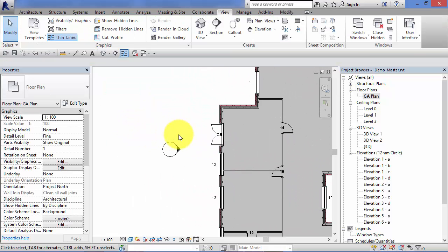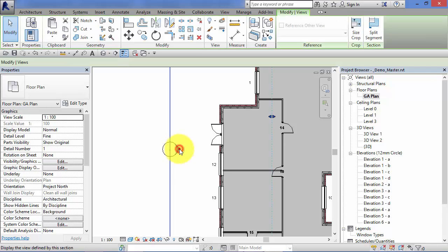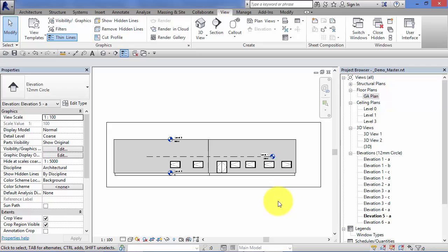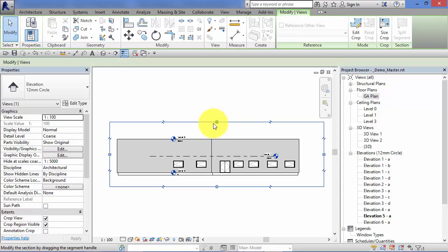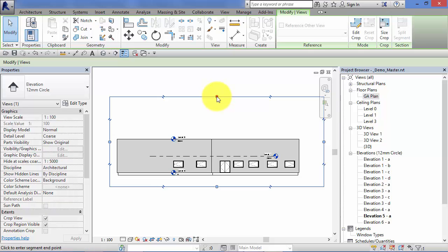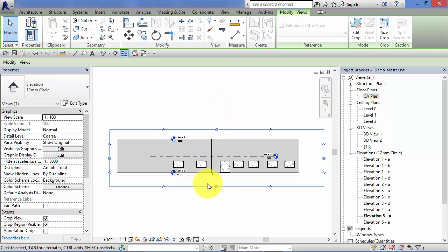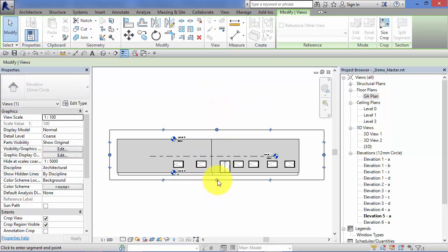As we said before, the filled in triangles act like hyperlinks, taking you straight to the views that they generate. And again, in elevation you can make adjustments to the height of the elevation, so you can crop that down to just what you need to see, and below. And again, we saw that width adjustment in plan. You can also do it in the elevation view itself.